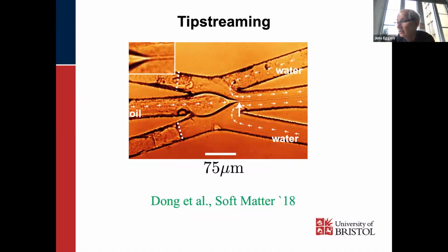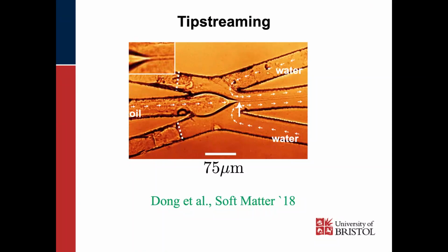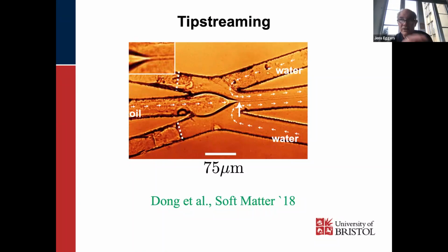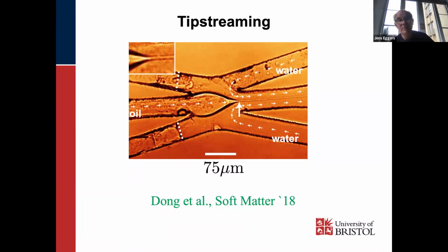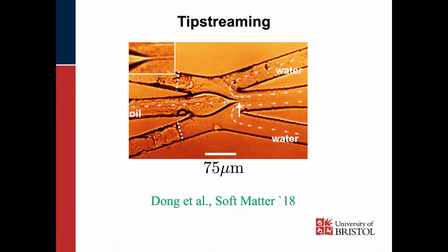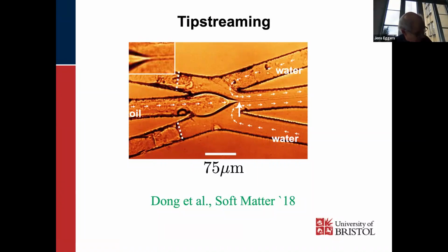I just expect that this result needs correction, because, as I've explained, near the tip Taylor's expression is not correct, because the real interface is not conical, but has a slightly more complicated form. In principle, in both the inner and the outer expansion, the effect of viscosity ratio can be included.